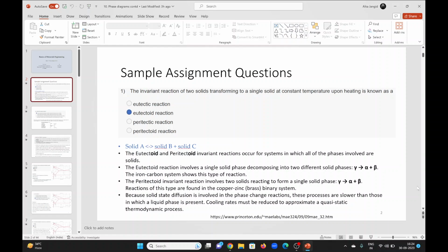Like they are negative and give free energy. Amorphous structures will require higher energy. They are metastable systems, your amorphous structures. So if you leave, for example, your nanocrystalline materials or your amorphous materials for a very long time, they will try to convert into crystalline structures.